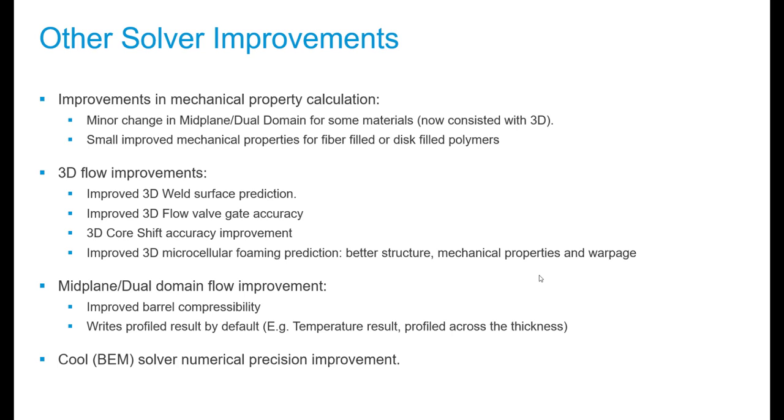We also made some improvements in the 3D core shift accuracy, as well as in the microcellular foaming prediction, particularly better structure and mechanical properties to be taken into account in warp. On the midplane and dual domain side, we had some improvement on the barrel compressibility, and we are now writing out